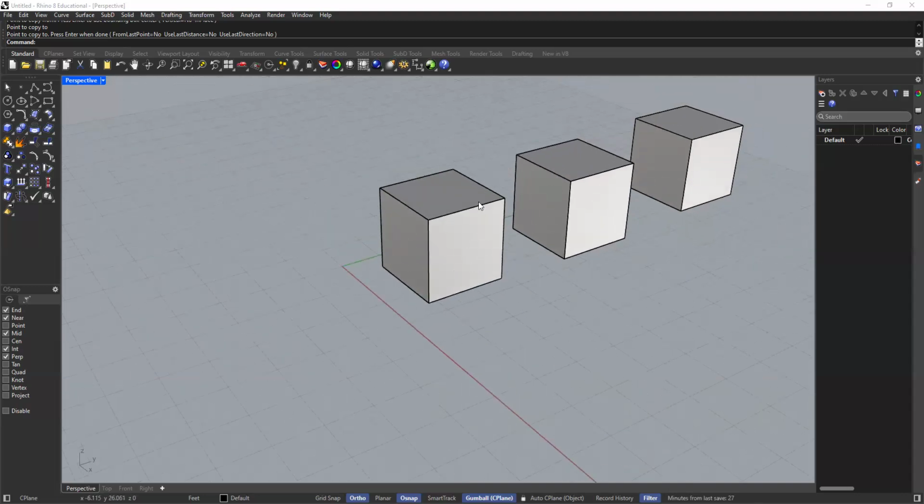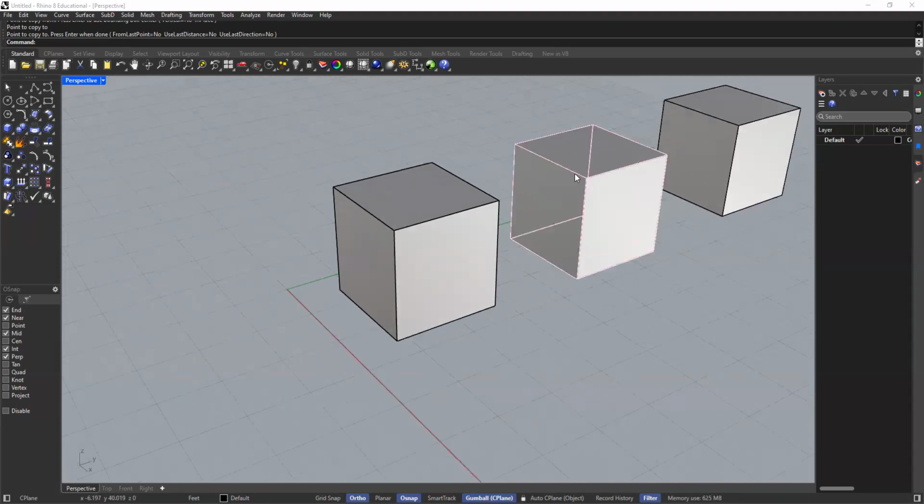So when you go about modeling and you find yourself with these selection menus, and it's going to happen, you'll at some point, depending on how you modeled, have different options. It'll be between a polysurface, a surface, and an extrusion. So hopefully moving forward, whenever you see these three different terms, you now know the difference, right?